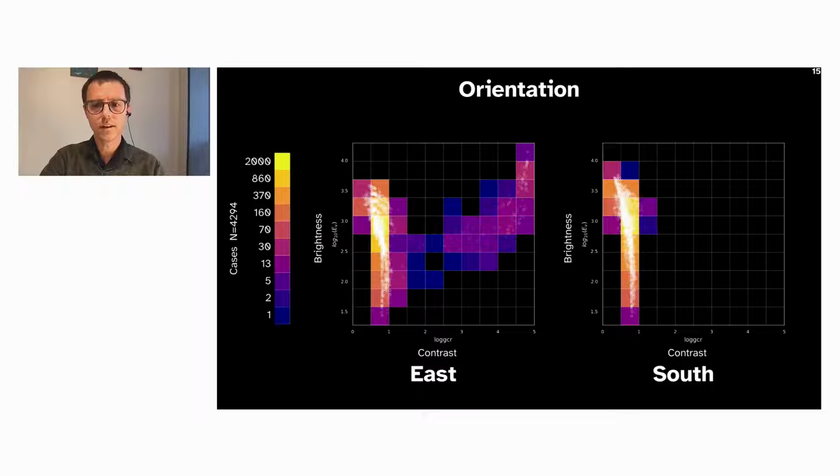The concentration of conditions within a narrow contrast band is typical for a single view location, and is why illuminance-only glare proxies are often considered accurate enough. But the presence of low-angle direct sun and specular reflection, which are the source of the high contrast cases for the east office, is the defining characteristic separating these orientations. And I don't think anyone would argue that orientation and latitude are not important for understanding daylight.